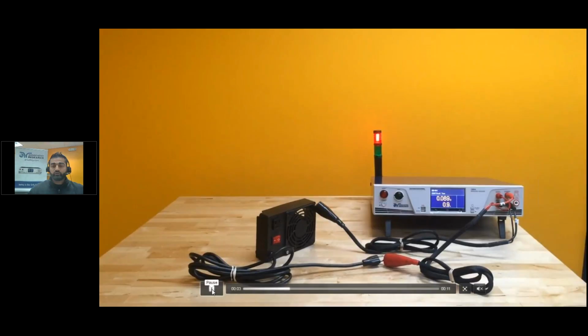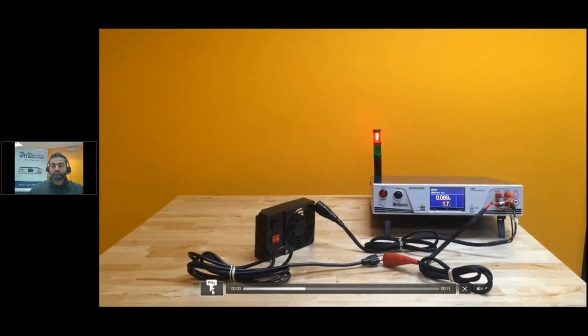When we press test for ground continuity, the first test we run is the ground continuity. If you could see, it's a 3-second continuity test. It's checking to make sure there's a continuous path from the red high current output to the black return lead. The path goes through the red ground pin, comes out to the metal screw here, and to our black return lead and goes back. So this is a continuous path. Our meter is reading 0.089 ohms, so 89 milliohms, and this is a good continuous path.